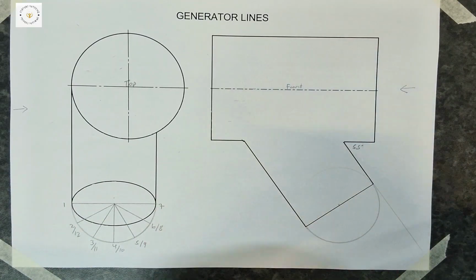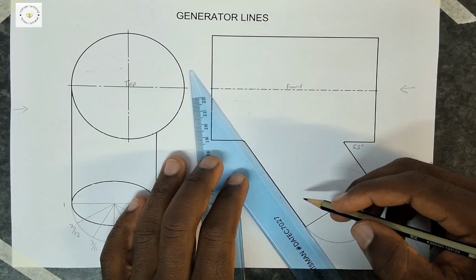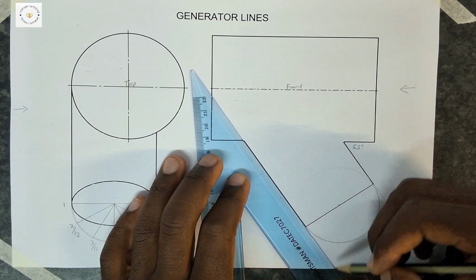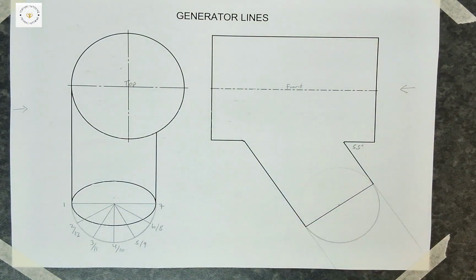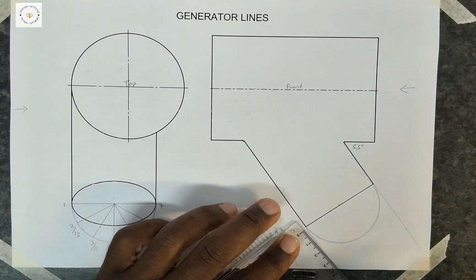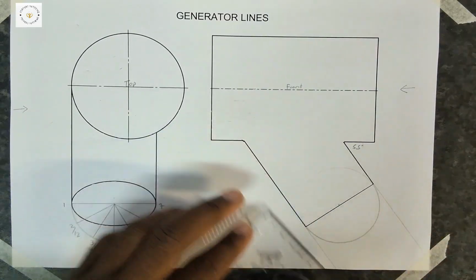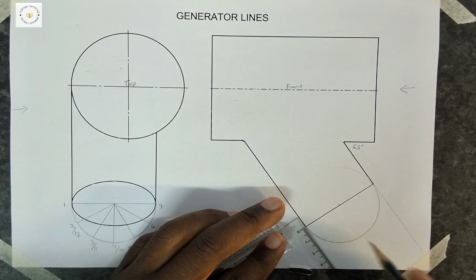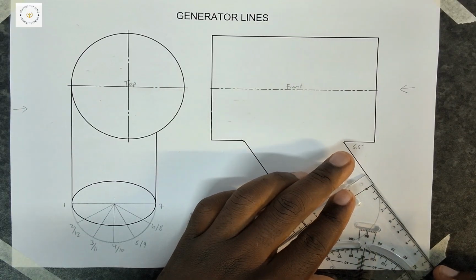But what I'm gonna do instead, to make things easier for us, is basically extend this other line. Because we don't have time in the exam, you also wouldn't have time to find a protractor for this. There are many ways to work around this, but I'm gonna find the easiest one so that we get to the point and solve the problem that we have here. So yeah, just confirming that's good. So I'm gonna measure 3 millimeters here, and also measure 3 millimeters from this side.